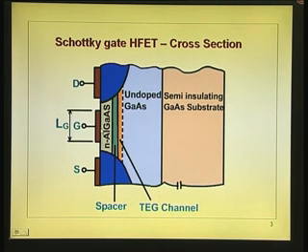So, when the gate voltage, let us forget for the moment that this layer is present, the entire layer will be depleted when VGS equals the threshold voltage of the MESFET, that is VBI minus VP0. Okay. Now, what we are looking for is what should be the gate voltage that I must apply, so that not merely this layer is depleted fully, electrons here also are absent or it is just about to conduct.